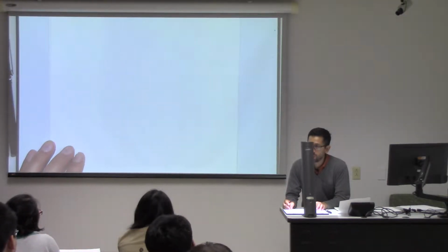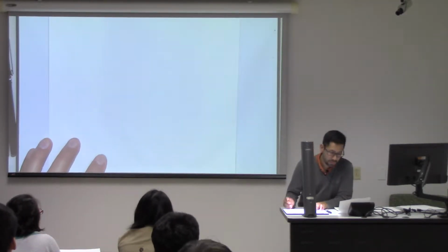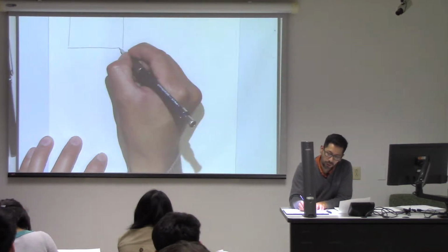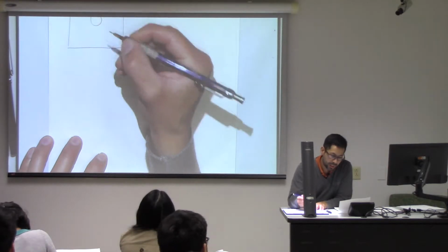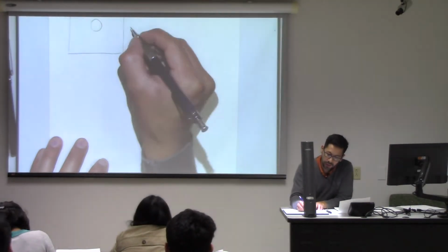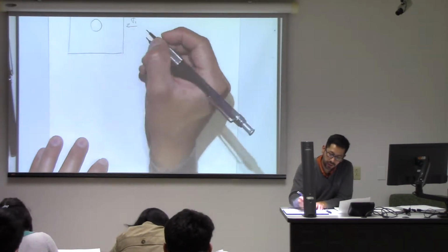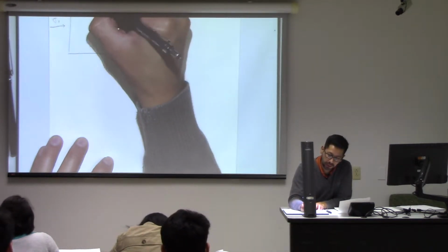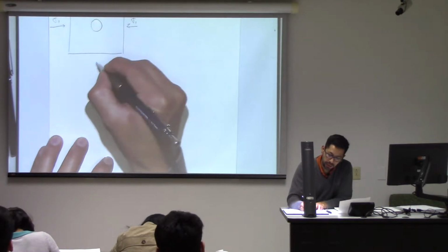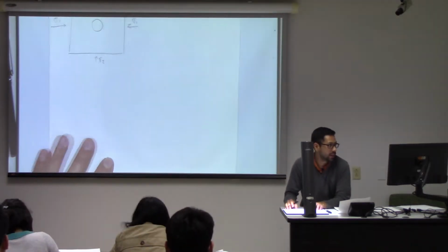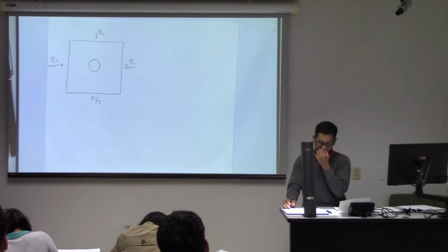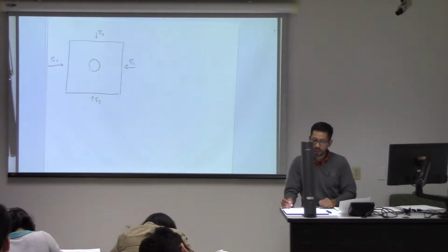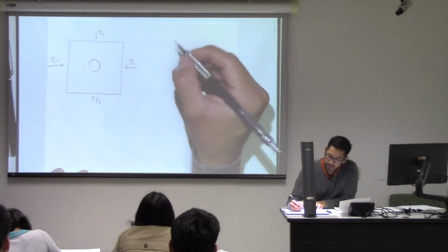Related to wellbore stability. Let's imagine that we have a vertical wellbore that is being drilled into conditions in which this is the maximum stress in the plane perpendicular to the wellbore, and this is the minimum principal stress in the plane perpendicular to the wellbore. With Kirsch's equations, as you already did, you can calculate what is the hoop stress, right?